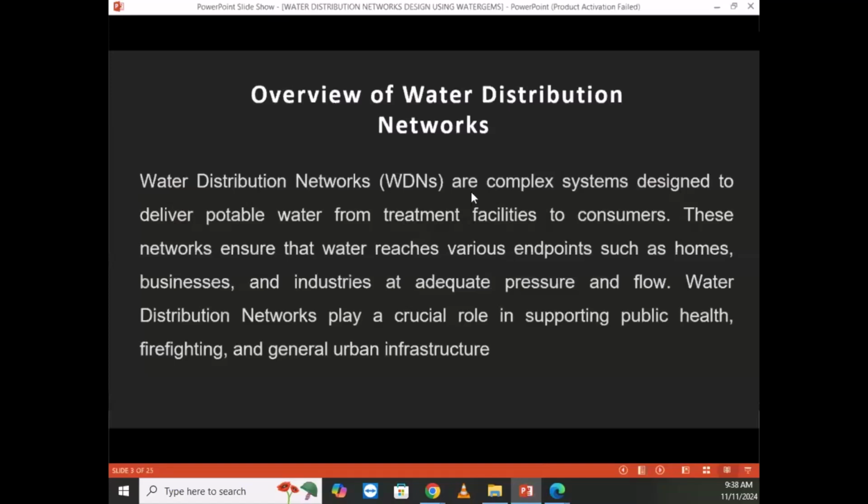Let me help you. There are some networks where, based on areas, there is a way of designing your network. As you said, that network is from a dam or from a lake. From the lake, yes, then we treat water. You take water from the lake, you pump it to the treatment plant to treat the water, and then you pump it to the main big reservoir, and from that big reservoir you do other transmission to the secondary tanks, and then from those secondary tanks you start distributing.